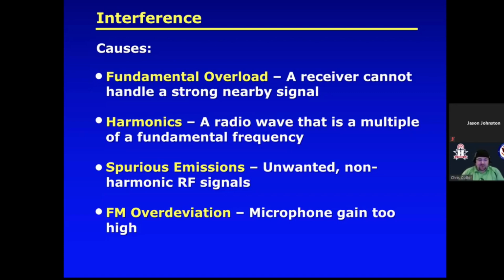So you have a cup of water, and you pour water into it. You've turned the microphone gain up a little bit. You're about 50%. You can still use the radio. You might start getting some complaints saying your signal is loud. Well, you can pour more water into it. 75%. You still have a little bit more. Once you get to 100%, that's it. Your radio does not have the ability to amplify your microphone signal anymore.